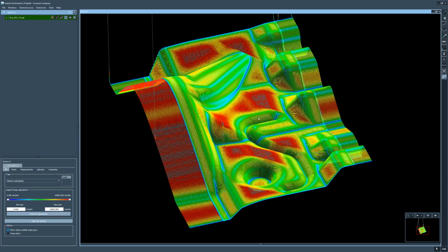And what do the gray parts mean? Gray is everything which is outside of the given range adjustments. And if we don't want this to be gray, we now have two possibilities. Either we increase the value here, as an example to 11,000, and then we don't see gray parts anymore. Or let's take a smaller number. We could take something like 10,050.